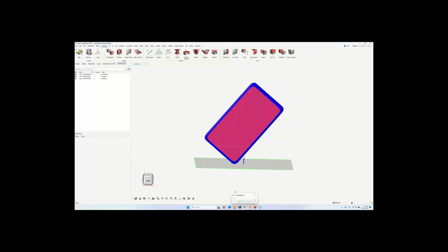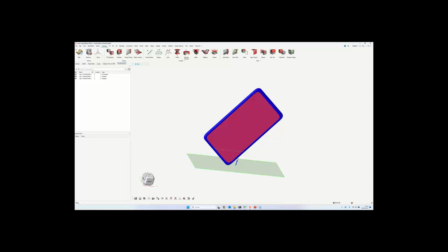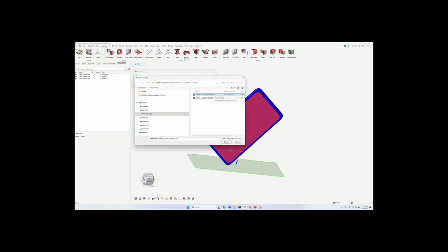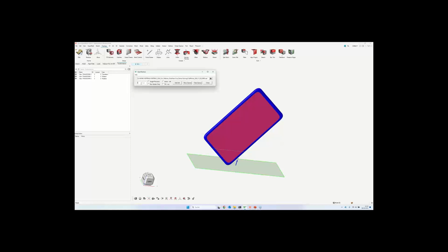And now let's get started with this model. After exporting it, we have created a nice small graphic user interface where you can just select your key or the 00.rad file, which contains all the information about the model itself, with all the data shown before that. So I open this model, I add a number of threads if I want to run here on my computer, so I put just 4, and I check that I would like to have, after the run is done, conversion from animation files to VTK and the time history into comma separated values, and add the job.